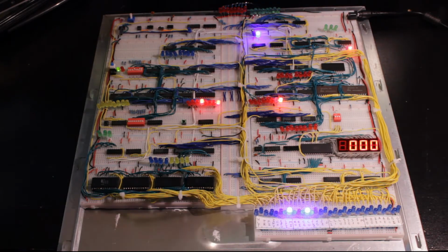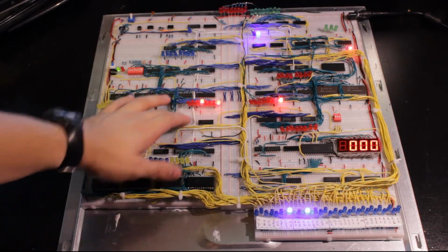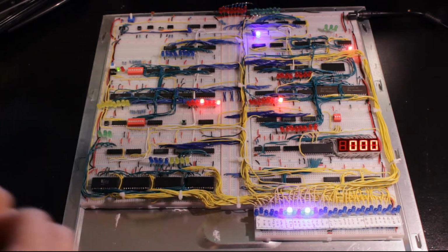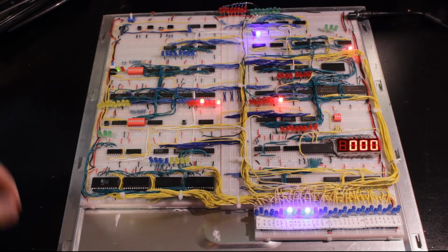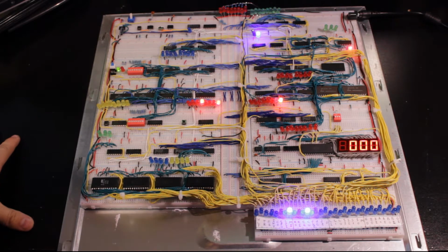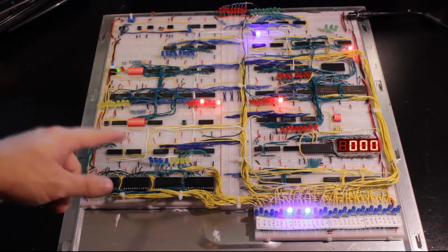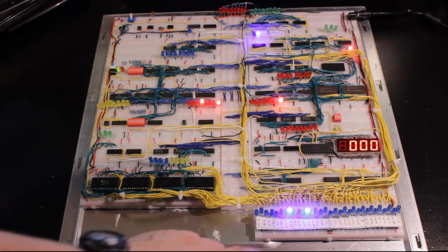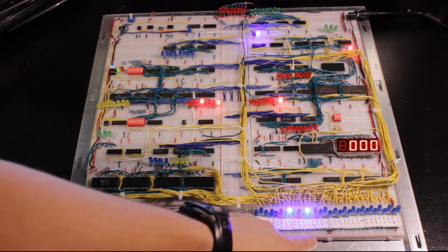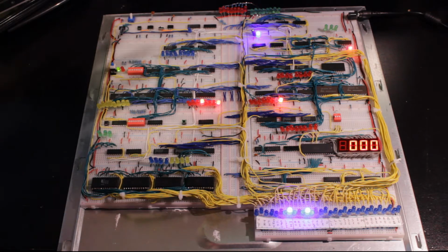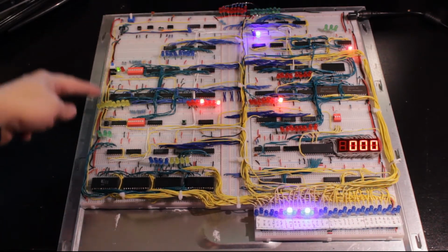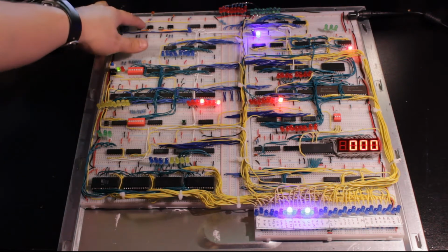Okay, so next we're going to want to step through this program in memory. So we're just going to reset everything, counters and all the registers. And I'm going to start execution. The very first thing that's going to happen is the fetch cycle, where we get the next instruction from memory and put it into the instruction register. So we take memory in and the counter out. Right now the counter is 0 and there's already a 0 in the memory address register, but the counter's coming out onto the bus and it's going to be loaded into the memory address register on the next clock cycle.